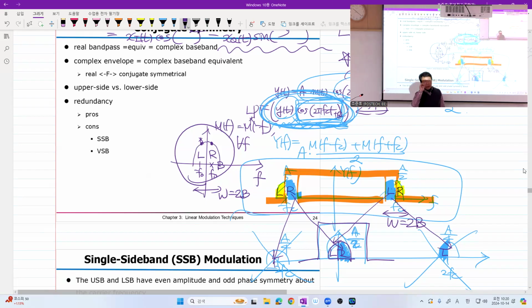However, in radio communication, if you purchase this band, you purchase that band in terms of complex sinusoidal signal. We just say that SKT, for example, purchased 5 gig to 5.1 gig from the government. That means you also purchased negative 5.1 gig to negative 5 gig hertz at the same time. So anyway, in the passband, DSB uses 2 times the bandwidth of the real baseband message signal.